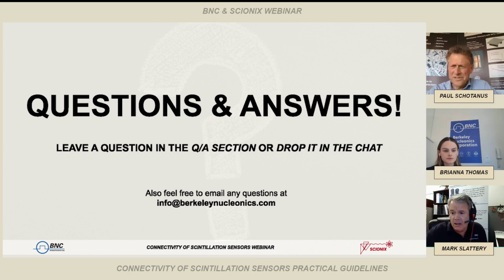There's still an interesting question there, Mark. For feeding a click detector signal into a digitizer, do we need an external amplifier? No, we shouldn't. You can feed a signal directly into a digitizer. Although maybe we want to mention that most digitizers do have a 50 ohm input. Yeah, that's okay. In this particular case, it's fine. For spill shape analysis, that's no problem. So a preamp is not necessarily a requirement.